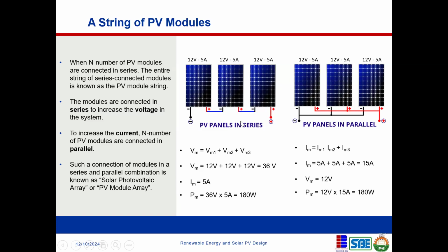Okay, when you have a solar installation, assuming that you have this solar installation connected in series, and then you have maybe dead leaves fall on just one of these cells. If these solar panels are such that they don't have diodes in between them, and just one of these cells is being covered by dead leaves, the output from this cell will be reduced.